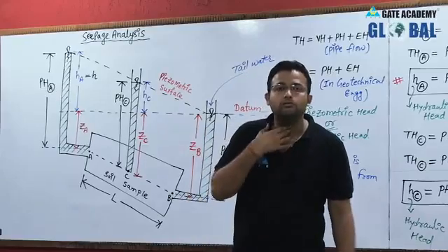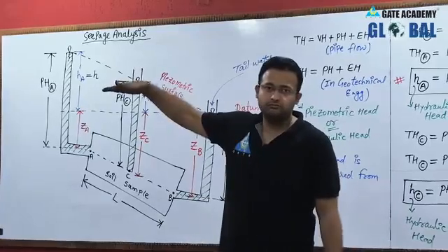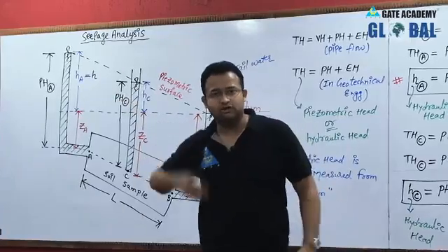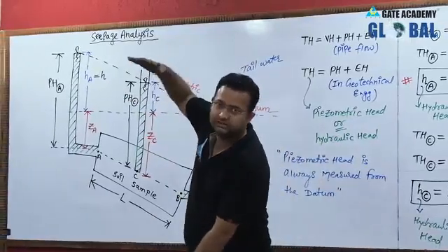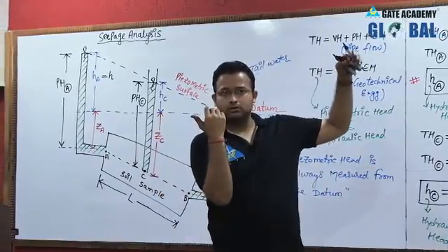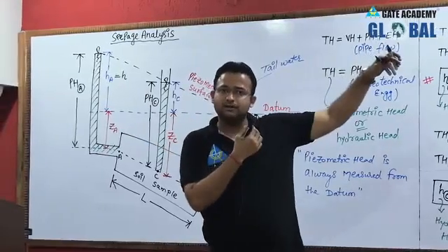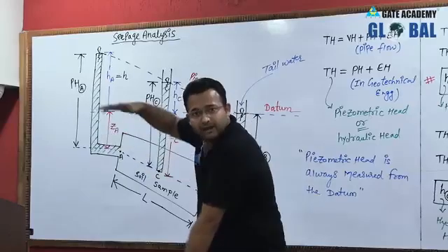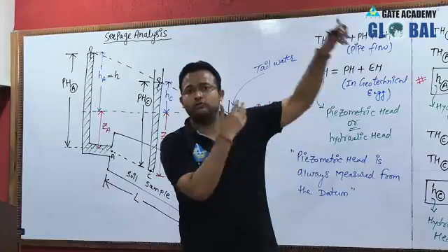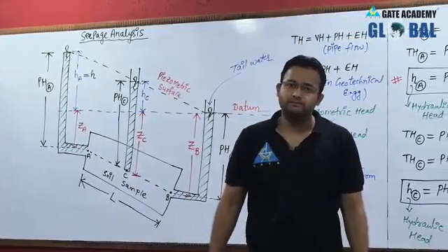Now one big flood is coming, of this much depth of water. This much depth of water flood is coming, or the river is coming, or the ocean, this much depth of water is coming. Can I flow with this now? Can this water take me? Yes, this time it can take me. Why? Because the available head is more. So it will apply higher energy, it will apply higher pressure on my body, that will be seepage pressure. This time it can take me with it.